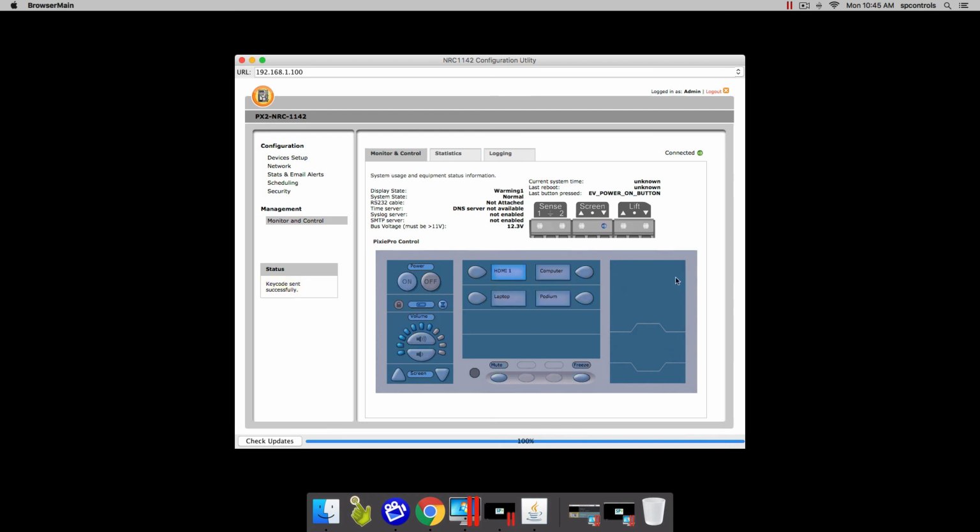Clicking on will activate the system. A moment ago, you may have seen the screen lift actually fire. That's the momentary closure for the relay to send the screen down in this scenario. Once the projector finishes warming up, this light will turn a solid blue, and the system will be ready to be used. You can then change the volume and the input select settings once the system finishes warming up. Until then, the panel will wait until it is finished warming up. Once it's warmed up, we can go ahead and control the system.